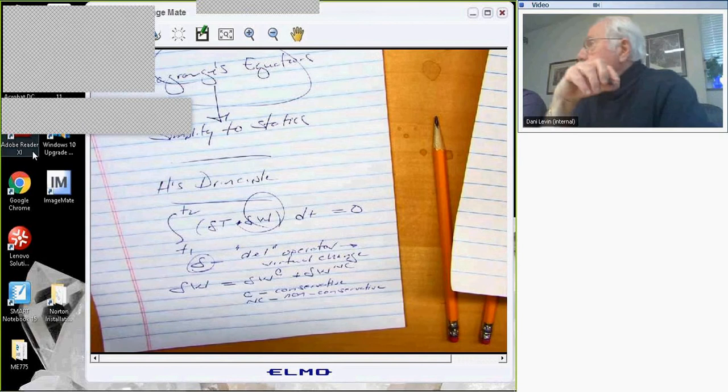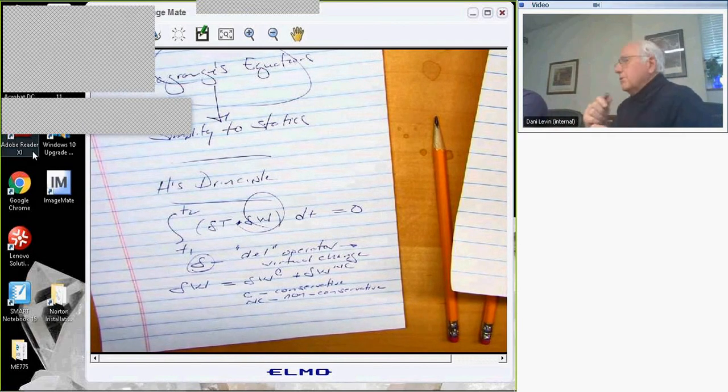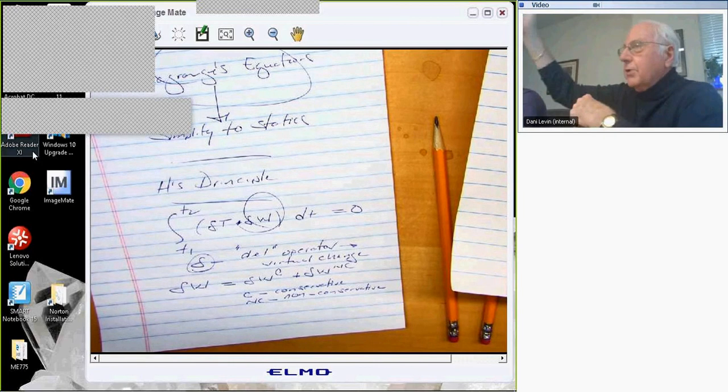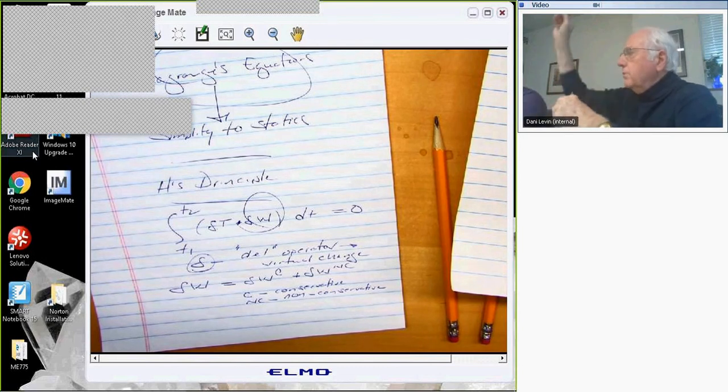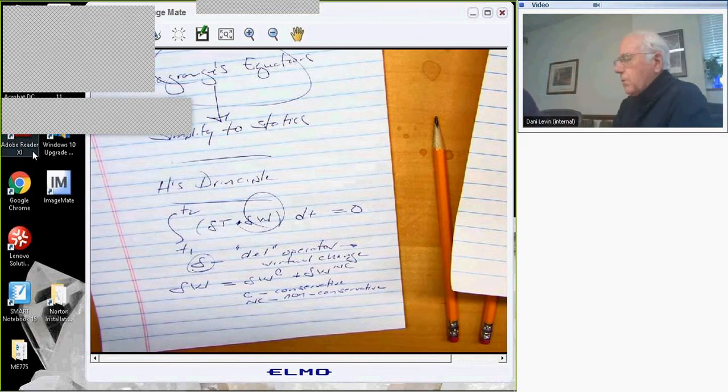Fluid forces, almost always, with not many interesting exceptions, are non-conservative. So that's why we need to think about non-conservative work and non-conservative forces. On the other hand, if you have an elastic structure, which is another part of aeroelasticity, right? It's aerodynamics plus elastic structures. Elastic structures can almost always be described, with one important exception, by introducing the concept of potential energy. Because an elastic structure is like a spring. You deform a spring and you let it go, it comes back to where it started. All the deformation you put into it comes back to its original position once you remove the force.